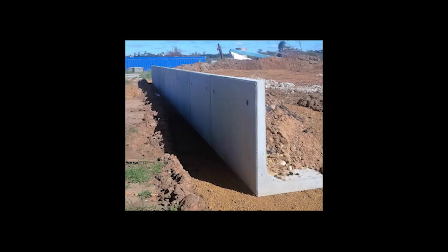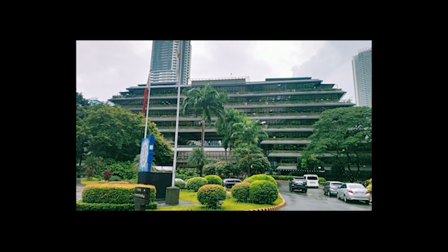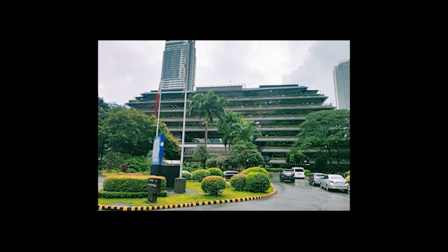Retaining walls resist lateral earth pressure. Earthquake-resistant structures transfer seismic forces through frames, bracing, shear walls, and foundations, but in the end, every structure has one mission: to safely collect, transfer, and resist loads. Because behind every strong building is a clear load path.